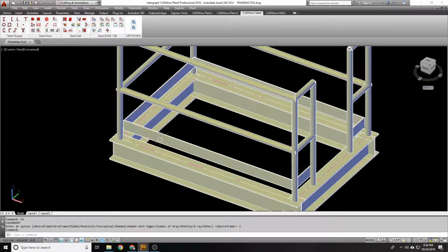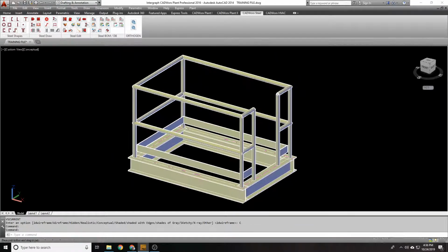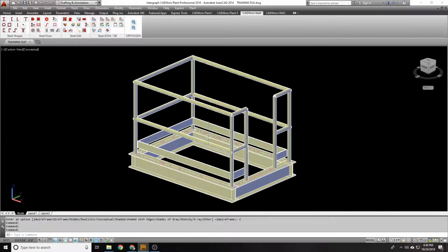Now, there is no base plate option in this version of CADWorx, so you're not going to see the base plate if you were to have top-mounted bolted pipe handrail. You're not going to see that base plate, but it shows at least generally where the post locations are. I would not use the handrail tool if you're going to manually specify post locations.